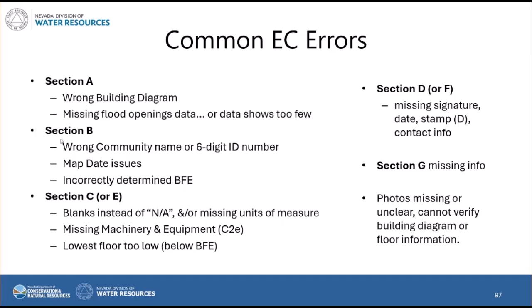Surveyors sometimes also forget to check the box that says feet. I know we're going to assume that it's going to be feet, but it's important to know that it's not meters or cubits or something like that. They've got to check the box that says feet.